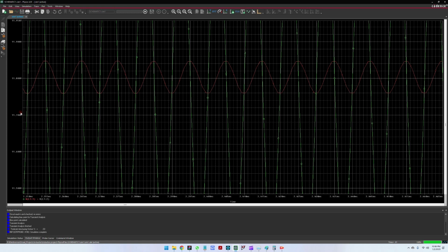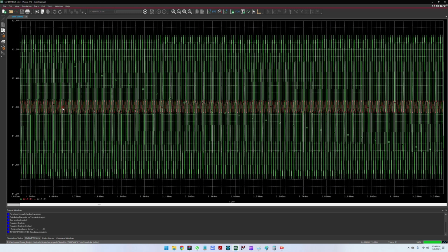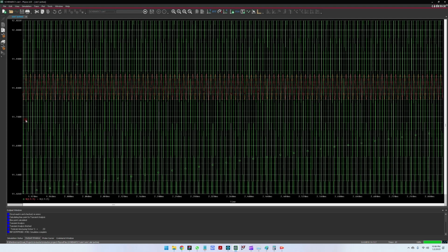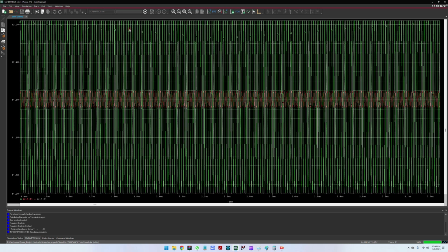This means that this is 20, 40. So it would be 20 plus 20 plus half of a decade. So this means that this is about 100 millivolts ripple compared to one full volt ripple. So it's 10 times smaller as a ripple voltage.